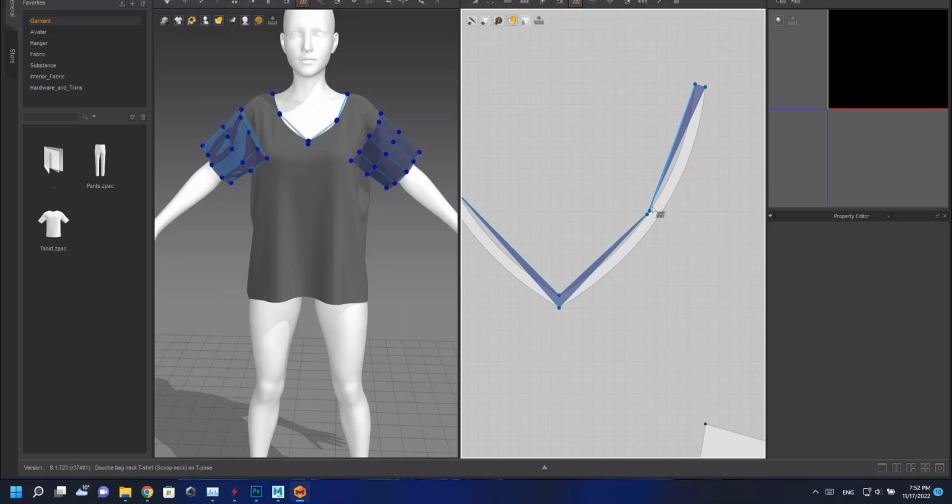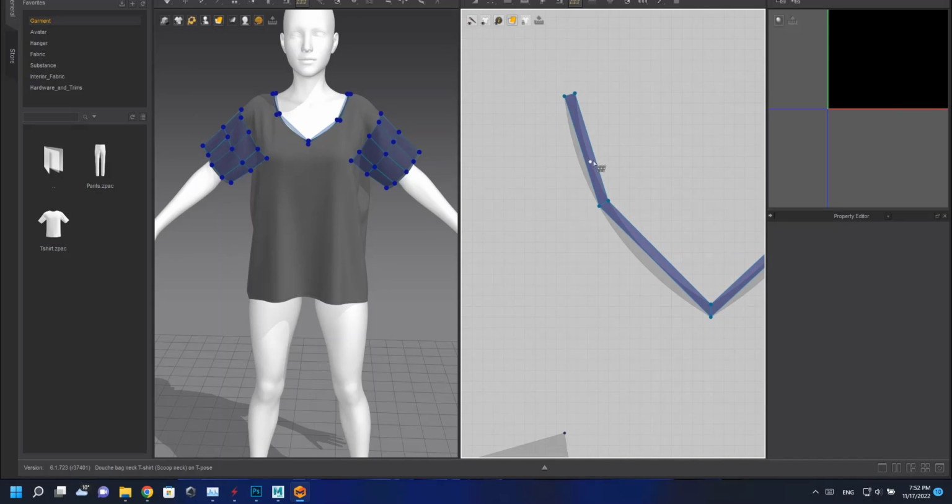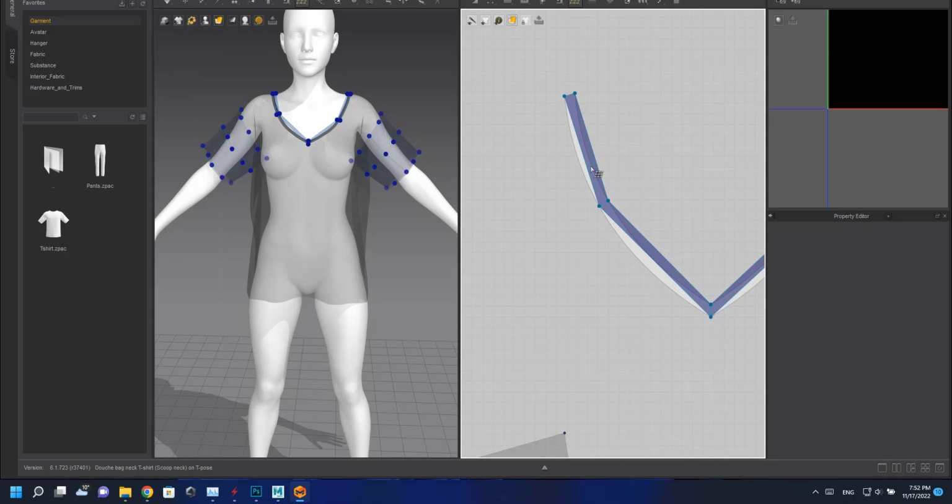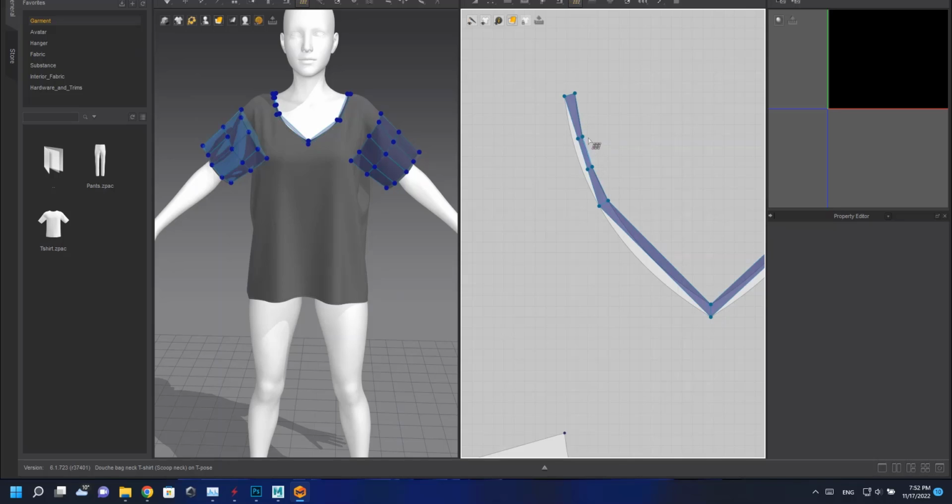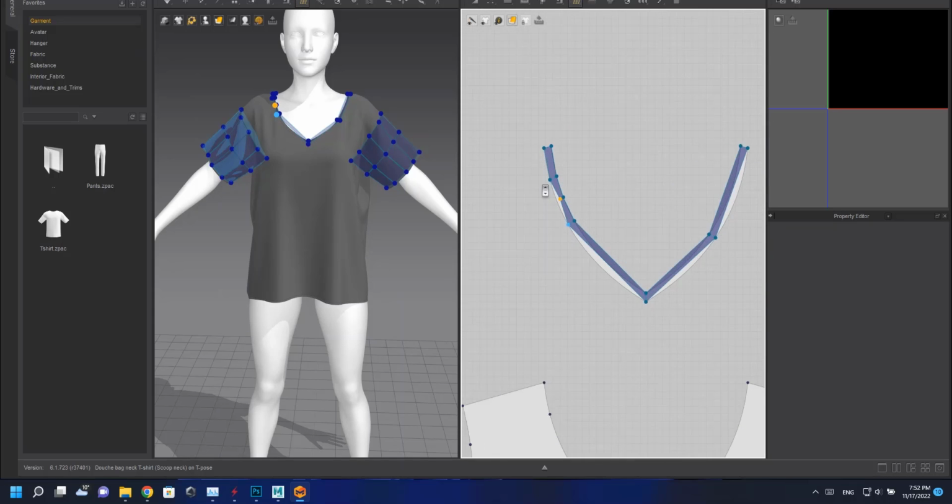There should be more space for the rest of the clusters. This method optimizes the system and gives higher quality textures when making materials. When making UV, care must be taken that the clusters do not cross the UV boundary line and that the clusters do not overlap. Save the output as OBJ without characters.